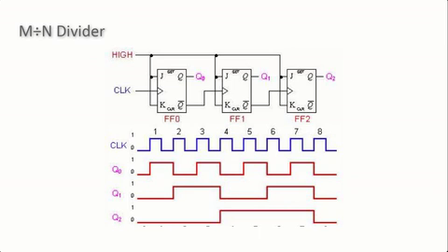In this circuit, the Q output of flip-flop 2 will be driven at 1/8 the frequency of the input clock. A ripple counter is easy, cheap, and as long as the propagation delay of the flip-flop is small compared to the period of the clock, extremely reliable.